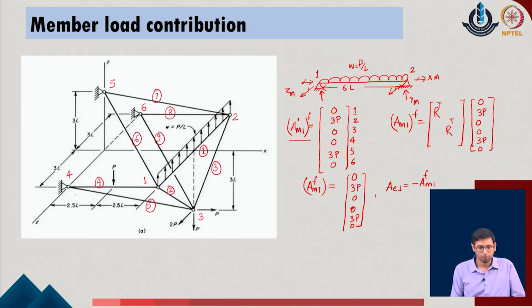In the similar manner, now I will go with the member number 4. I realize that for member 4 also it is a straight member. It will be considered first with the kinematically determinate form. So, the member is fully restrained, subjected to the load which is at the center of it. So, we will calculate the two reactions of the system which are P by 2 and P by 2 in the given system, and corresponding to it we realize that both these reactions are in the direction of y, no component along the x and z in the given system.